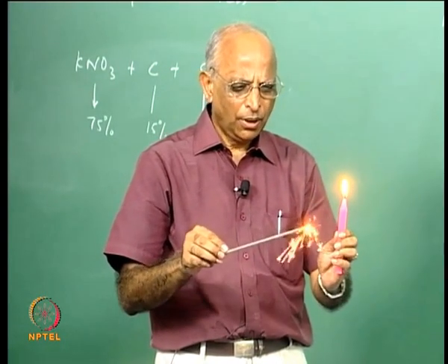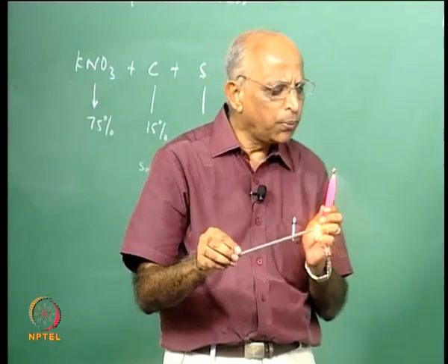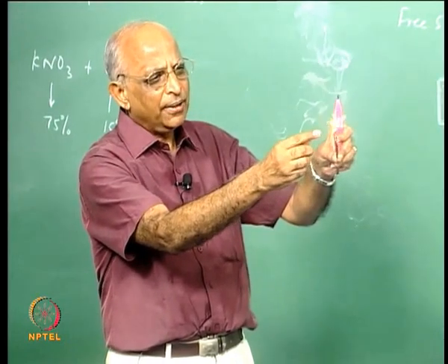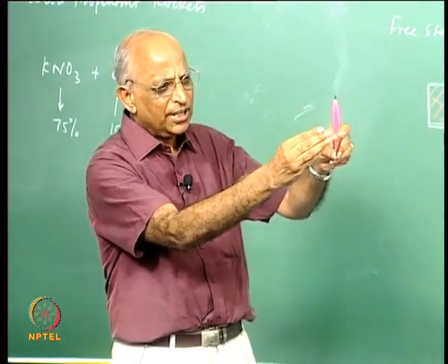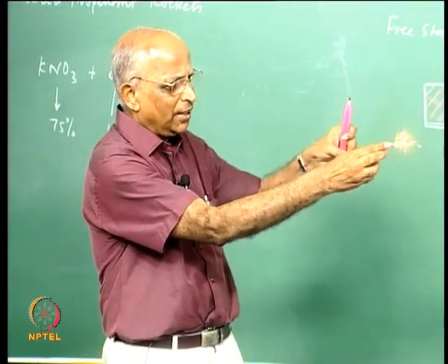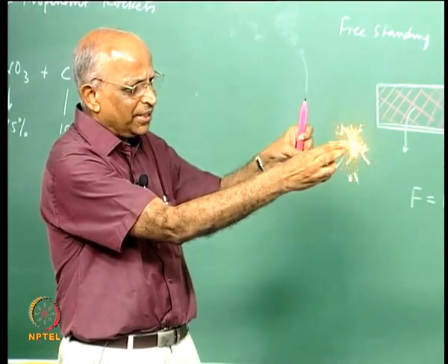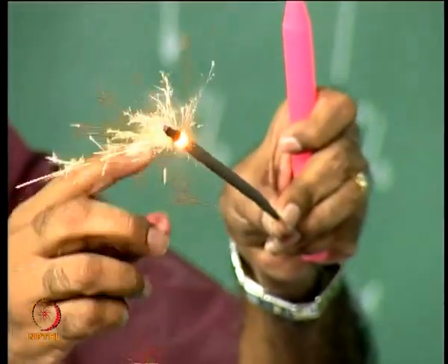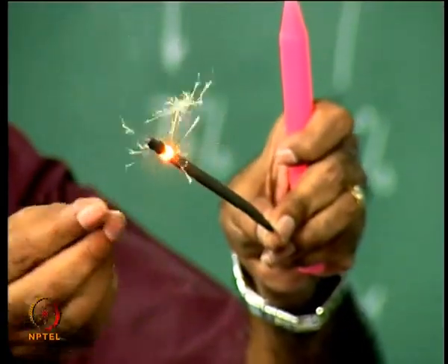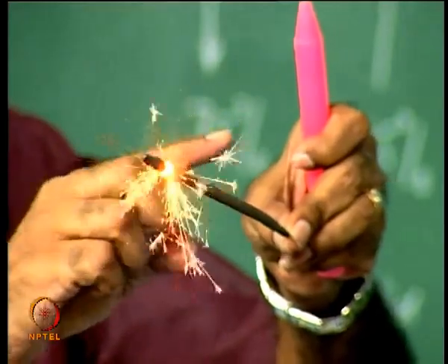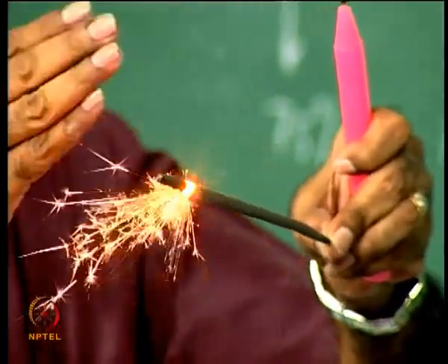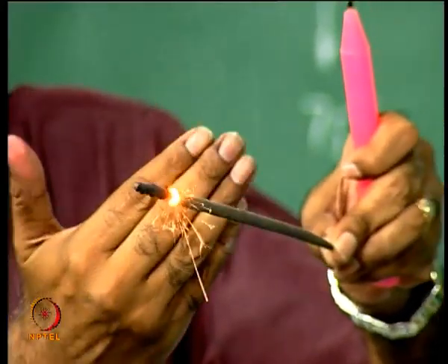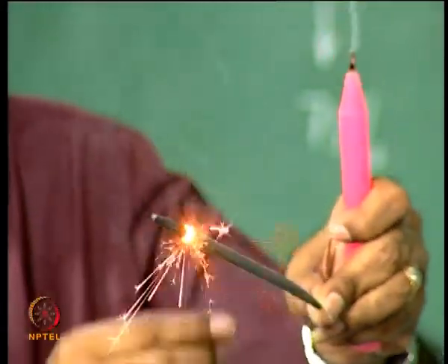How does burning take place? You have the surface which gets ignited, and this ignited surface burns the next surface, and so on. Therefore, you find that the surface is regressing at a particular rate. In this case the whole surface is exposed, but because it is air over here, the flame expands and is not able to ignite the surface. Therefore, the burning surface area is perpendicular to this plane and the burning progresses. This is the case of this composition.